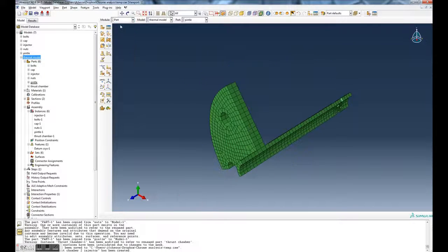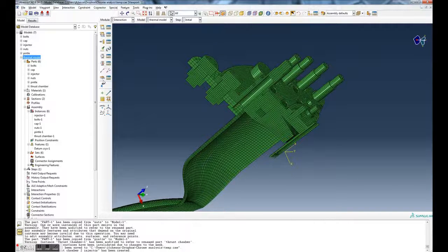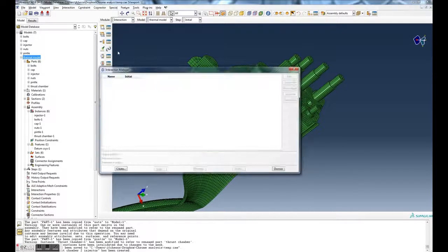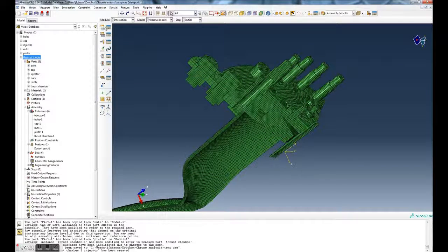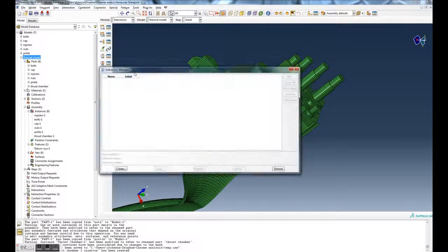And now, instead of using the scatter vector, which is the same as we had before, to put a local stiffness matrix into a global stiffness matrix, we're using this to extract the degrees of freedom for that element. You see we use it in D. So this vector is going to allow me to take the appropriate degrees of freedom for the first element or the second element or the third element. So for example, let's get E to be this third element, because that's where our example was.